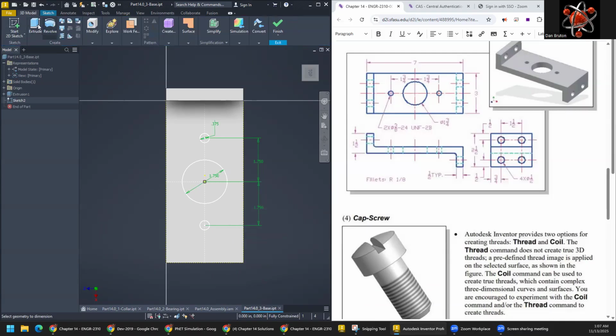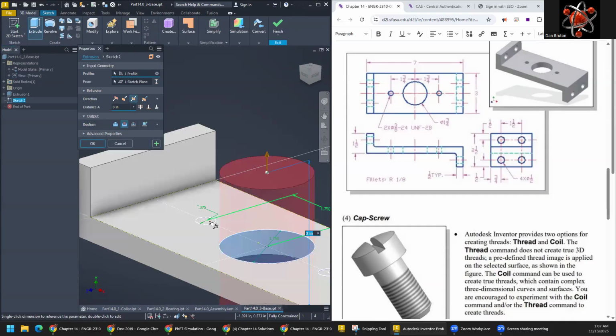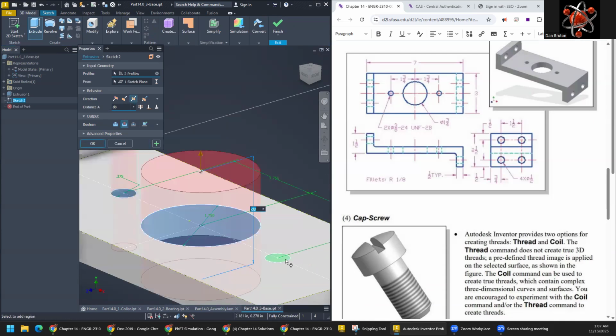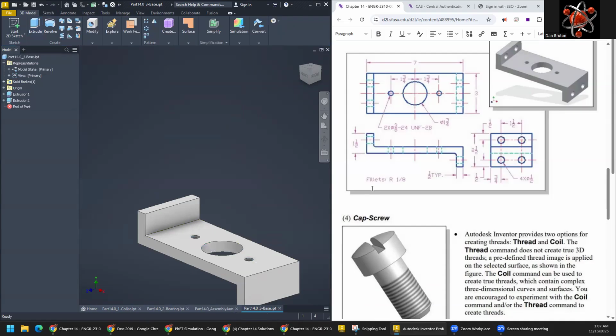All right, let's try the hole by doing a cut like this and pick all 3 of those shapes. Here it is. And there it is. It's doing overkill on that. We can just say through all if we don't want to do overkill. Got the 3 holes there.